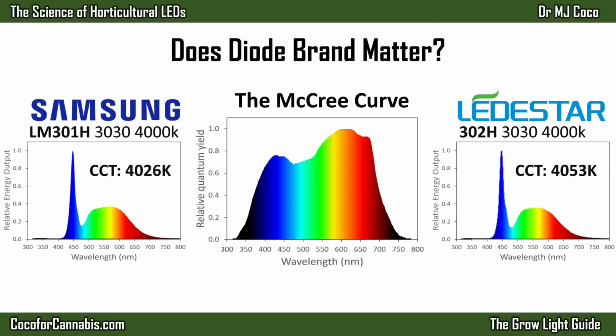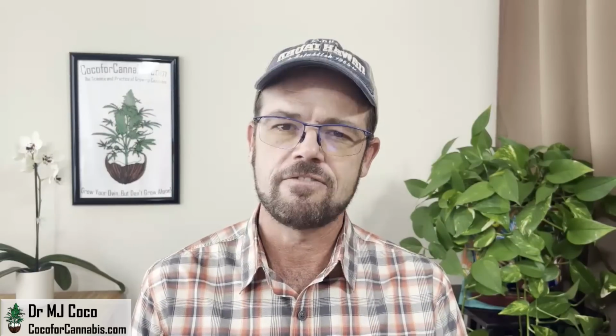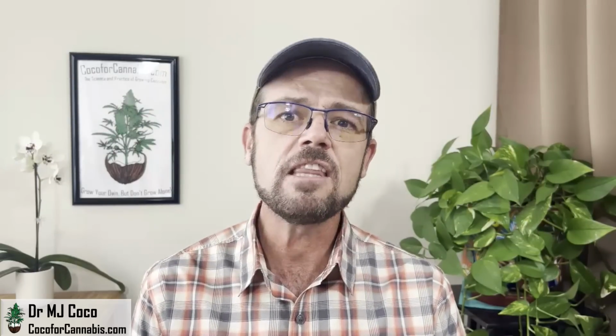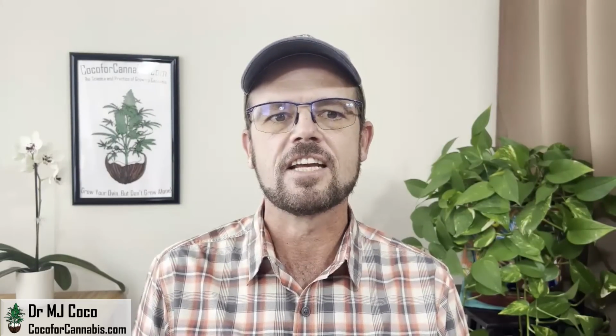Samsung makes 660 nanometer diodes, but most growers consider the Osram 660 nanometer diodes to be the best. Osram certainly makes a great 660 nanometer diode. However, they have several versions and bin ratings, and the efficiency varies considerably. If you find them on a cheaper fixture, they're probably the lower rated version. The top rated Osram diodes are among the best, but other brands have diodes that can compete.